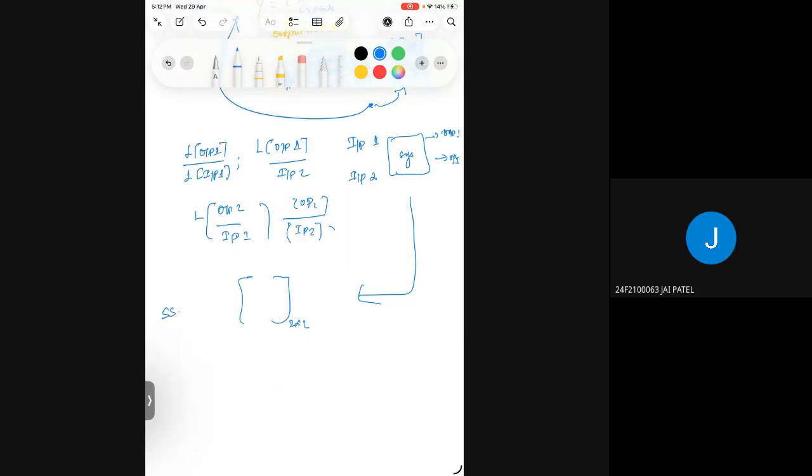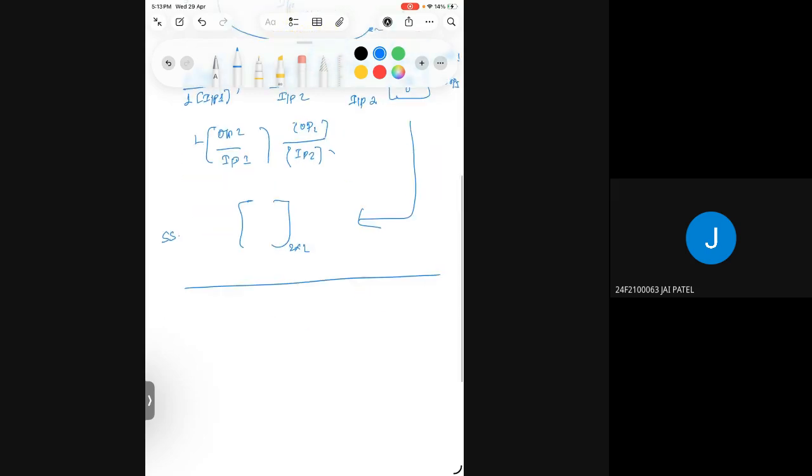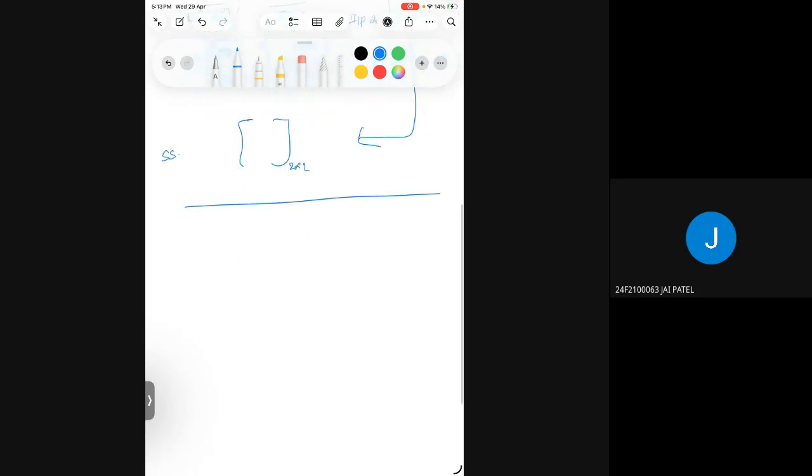But for simple systems like first order, second order, up to third order systems, you may use transfer function because using Laplace we'll be able to get it very quickly. And for state space, you would need a dynamic equation or the relation between it properly so that you can derive it from an nth order equation to n single order equations. Right. So far you have seen all these things. Just to warm up, I have told this. Chakravarti would have taken controllability, observability until then, I hope. So then we will move towards the controller design in state space representation.